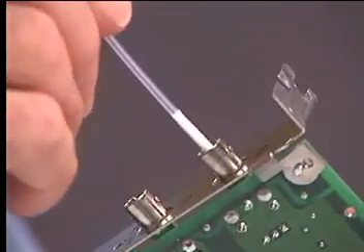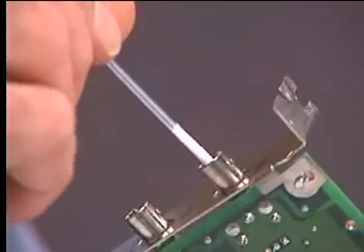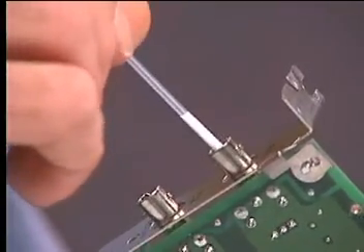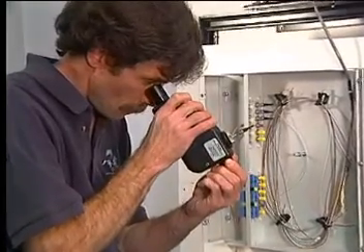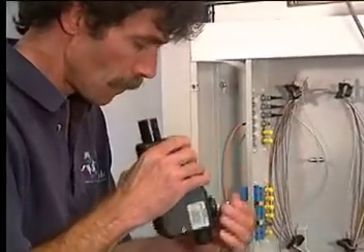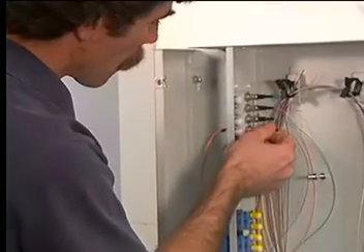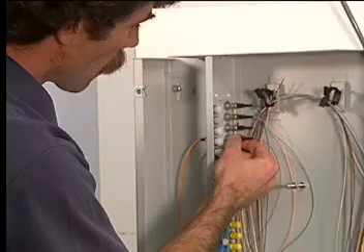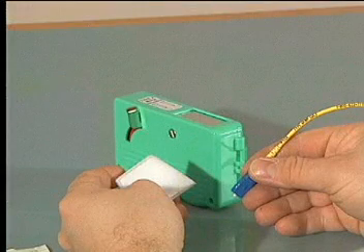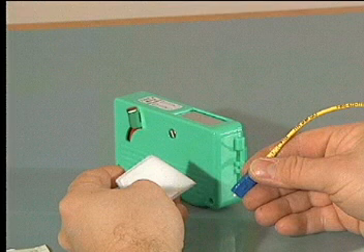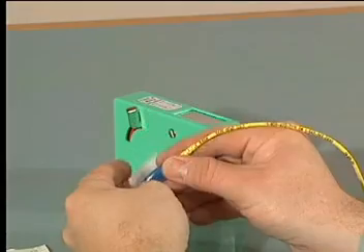Unlike a jumper that can be easily replaced or repaired, a damaged laser or detector can be extremely costly to replace. During any connector cleaning, keep the following points in mind. Always scope the connector before and after each cleaning procedure to verify cleanliness, and mate the connector as soon as it is clean. Avoid the use of alcohol products on high-performance connectors unless they are badly soiled. Then, clean all traces of alcohol residue from the connector.